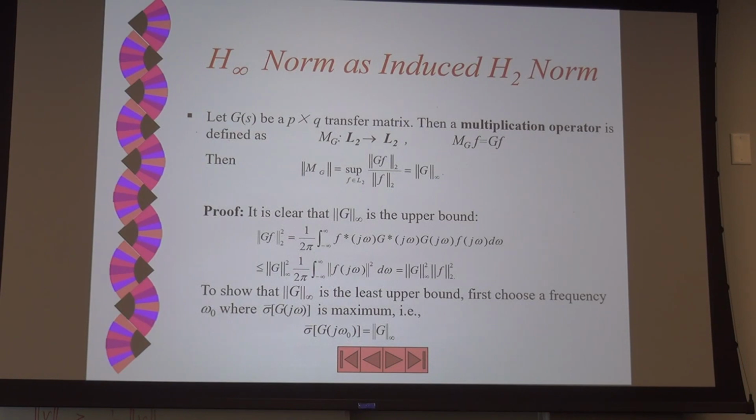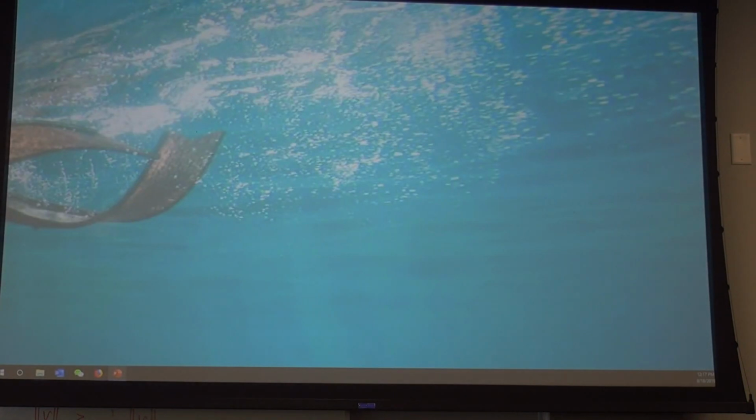Okay. H infinity norm. It's a worst-case norm I mentioned multiple times. And it's like an induced norm of a matrix. So, of course, this is no longer a simple matrix. It is a matrix that is frequency dependent. So therefore, it's frequency dependent. You still need to talk about maximum over omega. So this is the peak over all omega. And so that's a review.